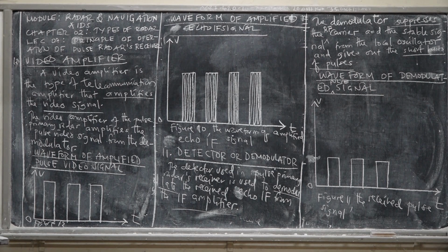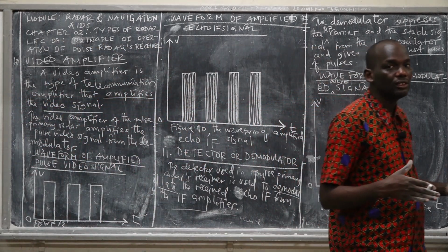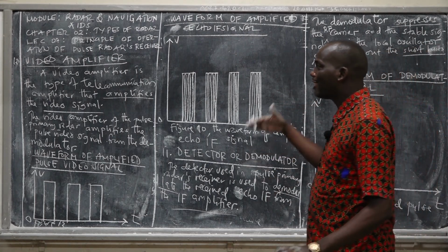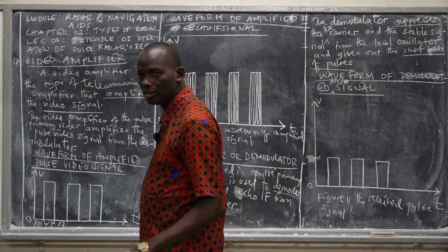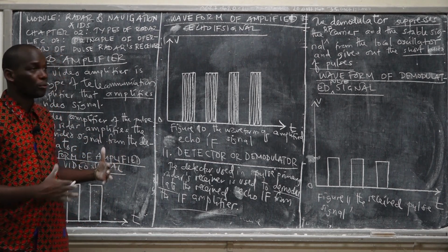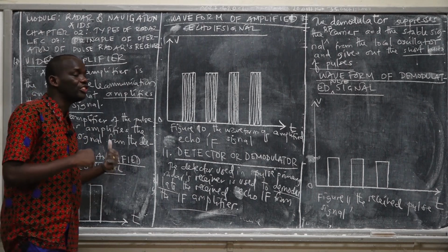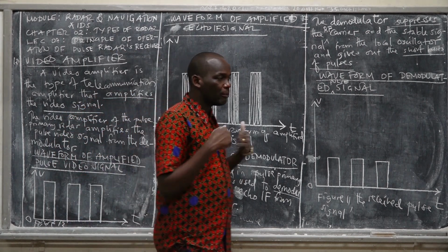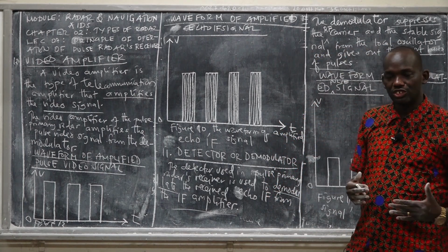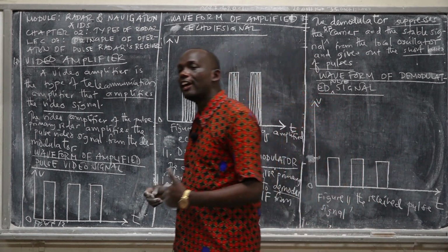In some pulse primary radar systems, stop writing, listen. After the video amplifier block, there is another block called threshold detection. Say threshold detection. In our general block diagram we don't have it, but let's explain to give you an idea. The primary function of the threshold detection in a pulse primary radar receiver is to make a decision, to compare the received signal with the transmitted signal.